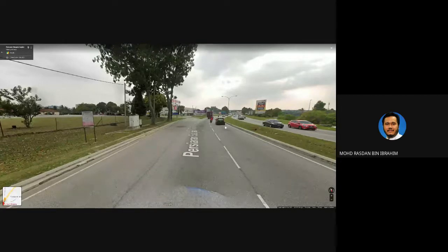Okay, so nowadays, the mistake is still here, but they have put lots of 2 rows of concrete barriers. Okay, they have put rumble strip. They have put signboards. They have put lights, blinking lights, to make sure that people slow down when entering this curve. Okay, but the mistake in the super elevation is still there. Okay, because it is difficult for them to correct the super elevation.